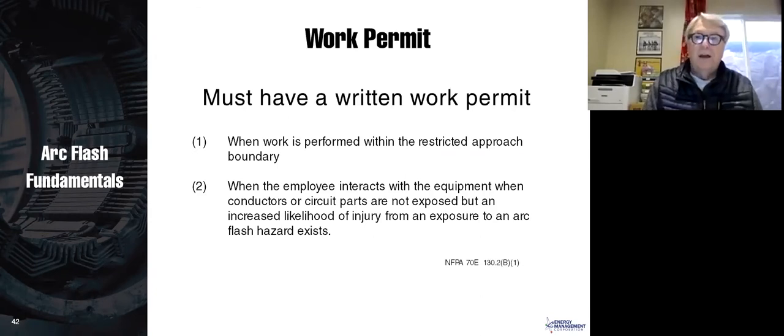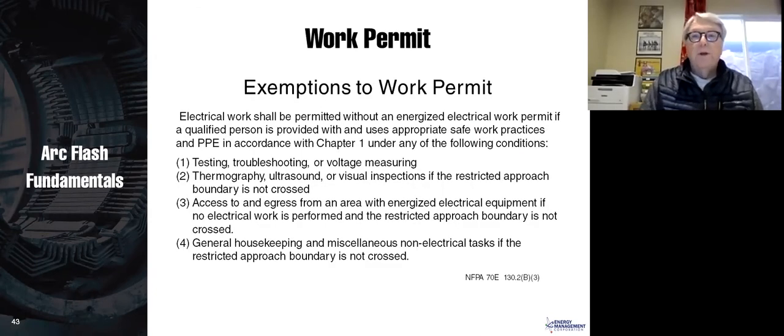You also have to have a work permit. When don't you have to have a work permit? If you're doing testing, troubleshooting, or voltage measuring, you don't need a work permit. If you're doing thermography, ultrasound, visual inspections, you don't need a work permit. If you're just going through the area or doing general housekeeping, you do not need a work permit. However, any kind of major work, you need a work permit.